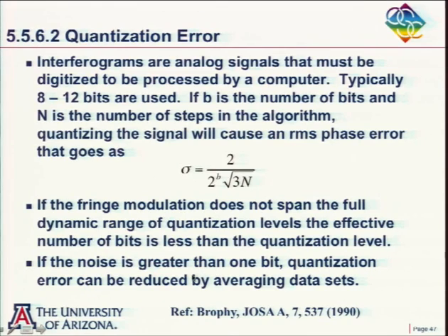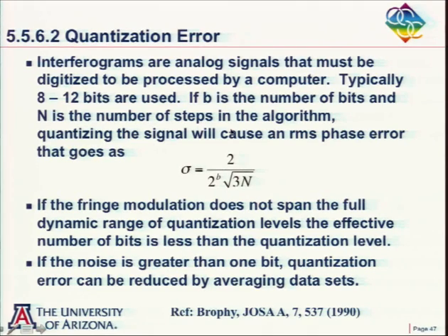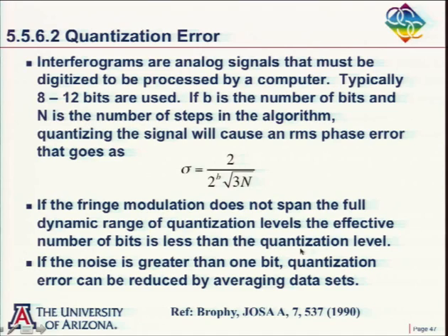And in this case, if our noise is real small, well, we're going to get the same measurement every time, and we're kind of stuck by whatever the number of bits are that we have. But if we have a little bit of noise, so this jumps around enough, then I actually can get better results if I average a lot of data. So sometimes a little noise is good. I think in real life, though, as long as you have 10 or 12 bits to begin with, you probably don't even have to worry about this last item down here. But it's kind of interesting.